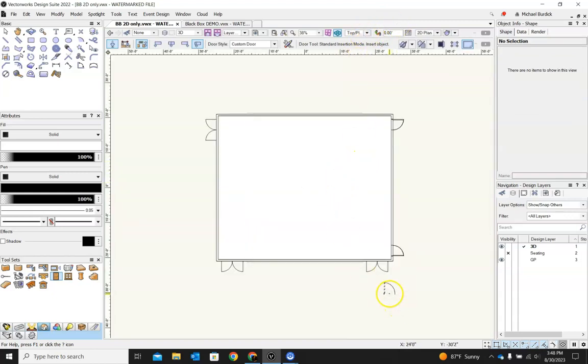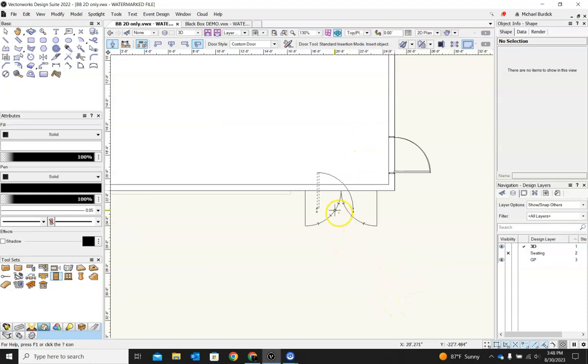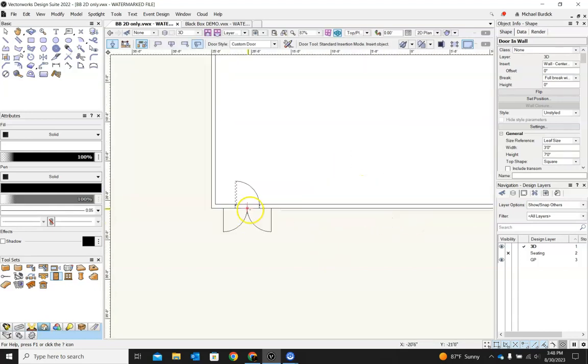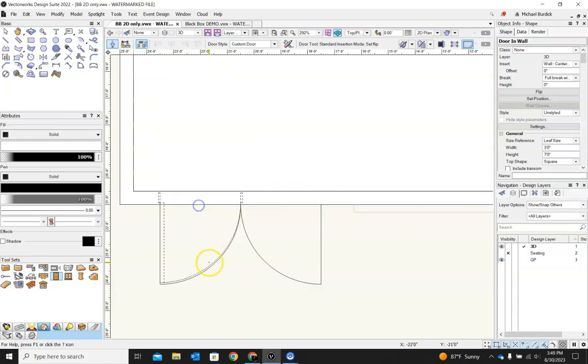Go back to top plan. If you have a number pad, I just pressed 0 as the hotkey to get us in there. With snapping, it just drops right in over our previous drawing. That saves a lot of time.